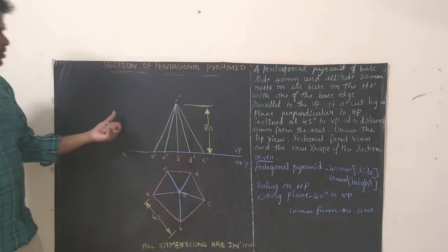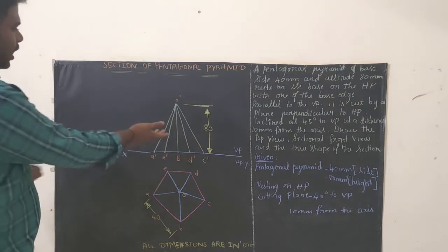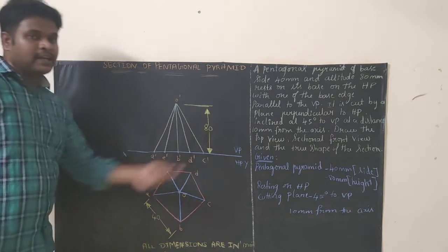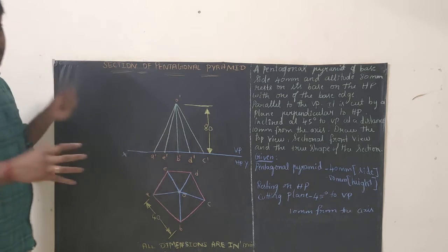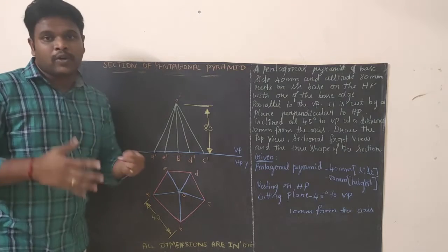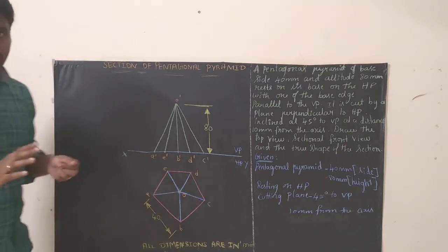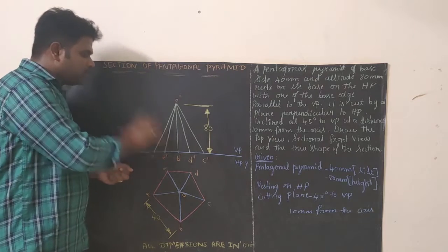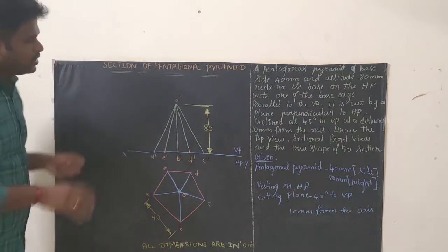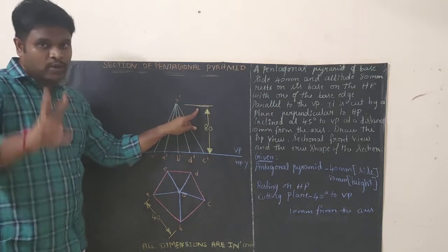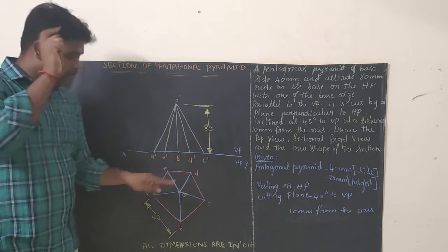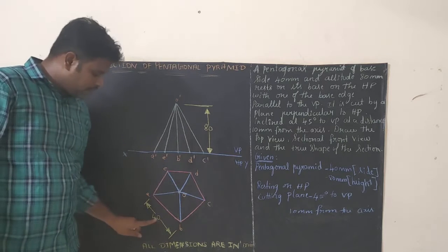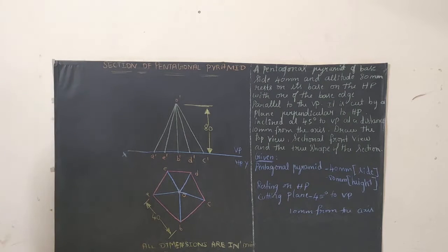So this is the way you need to dimension. Till now I have dimensioned mostly on the left hand side. But this time I have dimensioned the right hand side. The reason is we need to do some work on this side, so if I dimension here it will be clumsy. It depends upon what type of problem we are approaching. In this problem, if you dimension here, it will be somewhat of a disturbance, so I dimension the right hand side. This is the extension line in 2H pencil. These are the dimension lines in H pencil. The arrow is here, and 80 should be written with your HB pencil. Same thing here: extension line 2H, dimension line H, and 40 in your HB pencil. Right now we have drawn the front view and top view diagram.